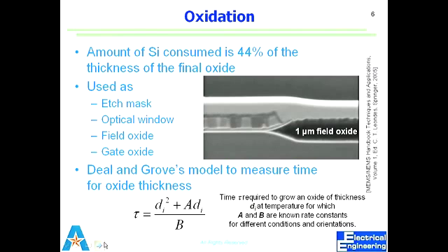So that doping has happened in the z-axis. So what is the big deal if you cover the top, right? It's not just the plane that we cover, we make trenches between devices and we cover those trenches with silicon dioxide, right? This special way is what we call shallow trench isolation, we'll look at that as well.